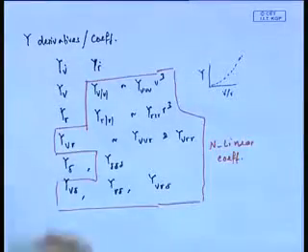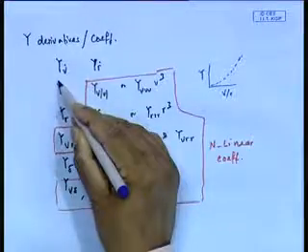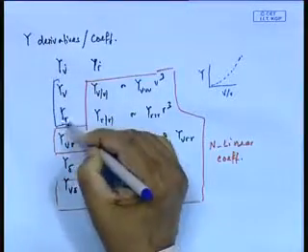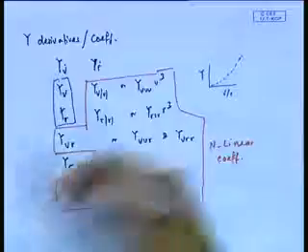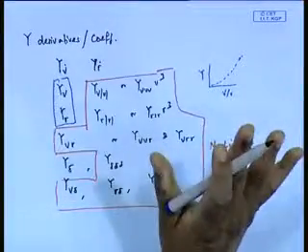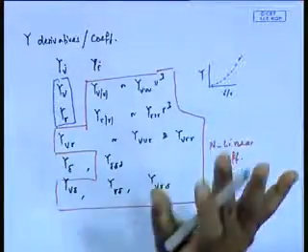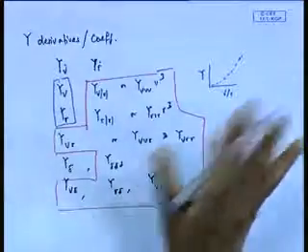See now, I come to the next part, the captive model test. Obviously, one of the biggest jobs therefore is that, well, I know the derivatives. Of course, I know only the linear ones, that is, I basically know this and the corresponding n as far as my directional stability with control fixed is concerned.